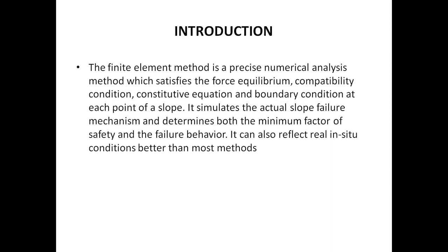SRM method is basically a numerical analysis which satisfies the force equilibrium, compatibility condition, constitutive equation, and boundary condition at each point of a slope. It simulates the actual slope behavior mechanism and determines both the minimum factor of safety and the failure behavior. In addition, in previous methods like LEM, we can have only the factor of safety, but in this method we can also have the stress strain condition in the embankment. So it reflects the real in situ condition better than most of the available methods.